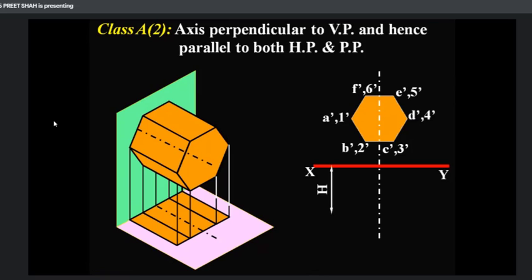Now here there is one question to all of you. Why should we give two names at each corner? Who will say what is the answer? One for the top surface and one for the bottom surface. Very good. Because if you see this object from the front, the top base and bottom base are merging with each other. So all the two bases merge into one shape, and that's why we give two names here. One in alphabetical order for the lower base and numerical order for the top base. So A dash comma 1 dash, B dash comma 2 dash, C dash comma 3 dash.